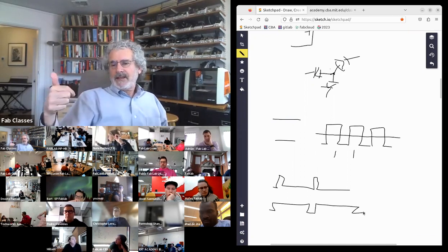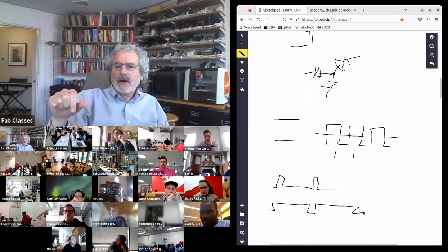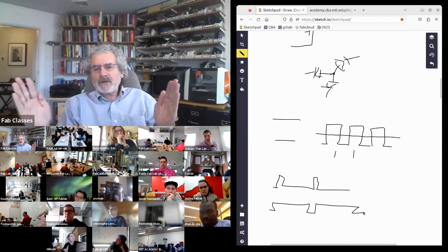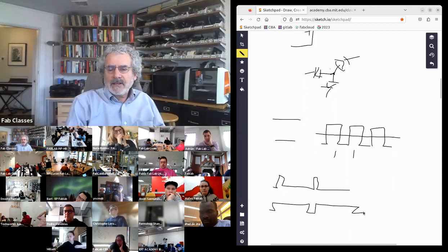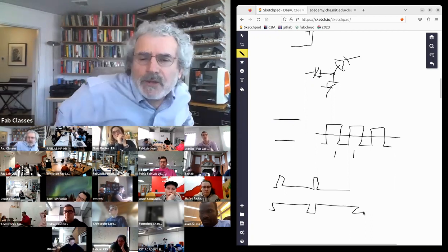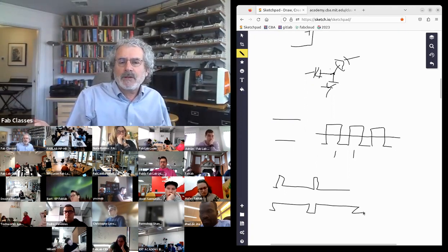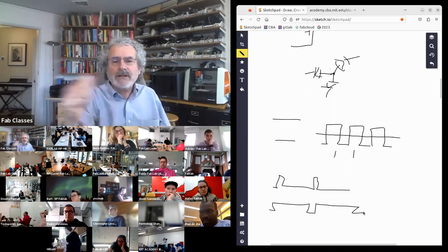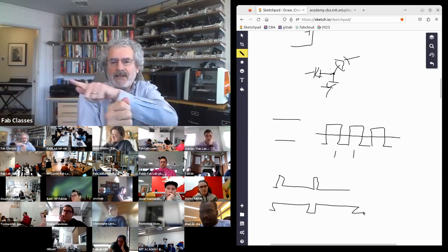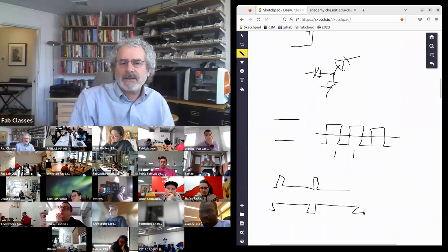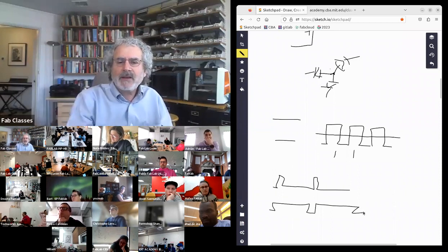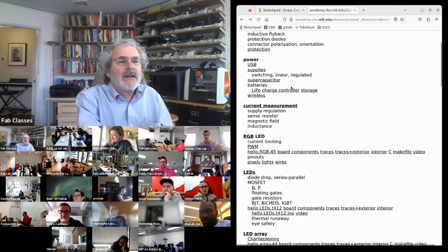And so by switching the LED between all on and all off, and just by varying the duration, we vary the brightness. And so that's how you control them. And a good way you can test if an LED is pulse width modulated is if you shake it really quickly, what you'll see is discrete little pulses of light, depending on how fast it's being pulsed.